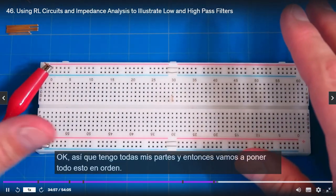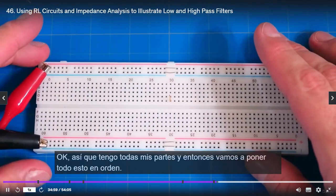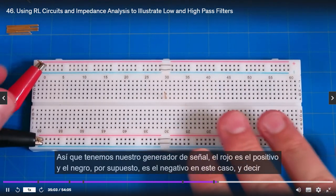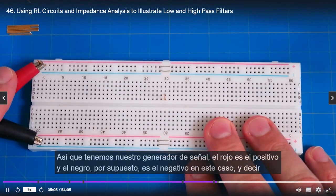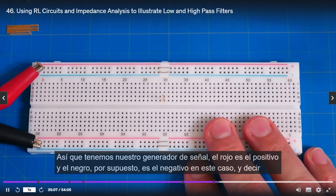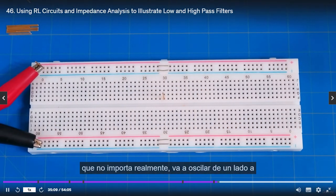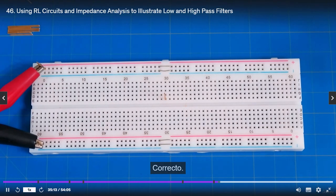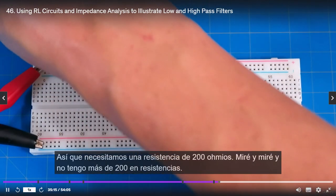Okay, so I've got all my parts, and so we're just going to put this thing together, all right? So we've got our signal generator. The red is the positive, and the black, of course, is the negative. In this case, since it's AC, it's not really going to matter. It's going to oscillate back and forth, but just as a reference. All right, so we need a 200 ohm resistor.